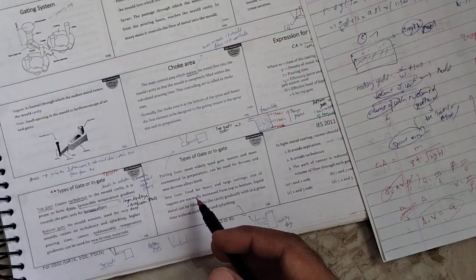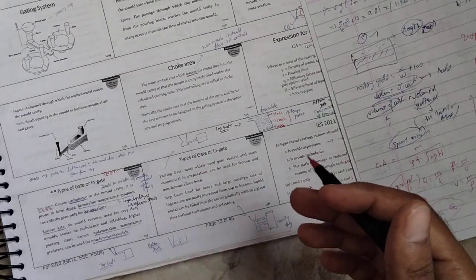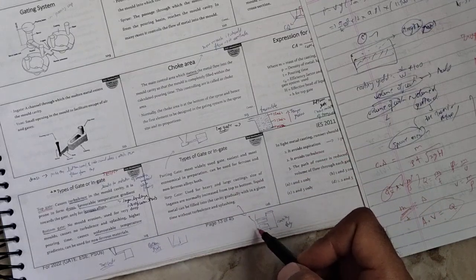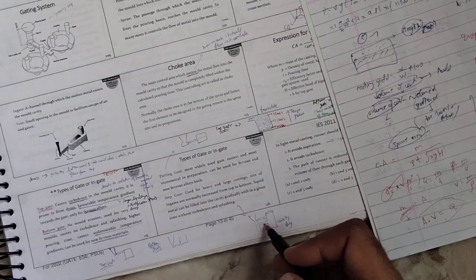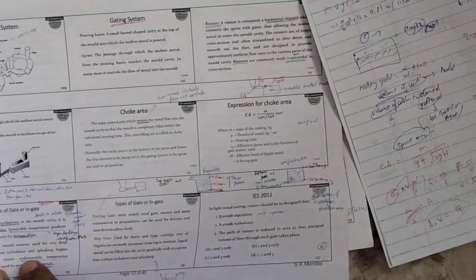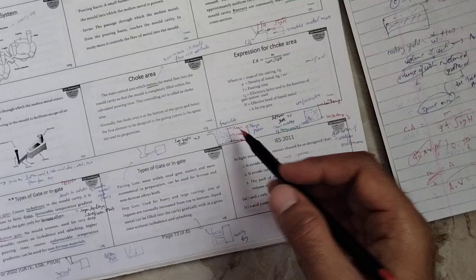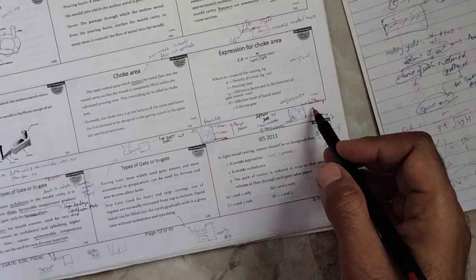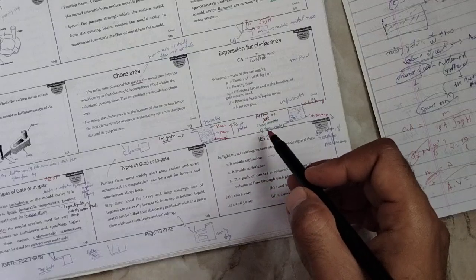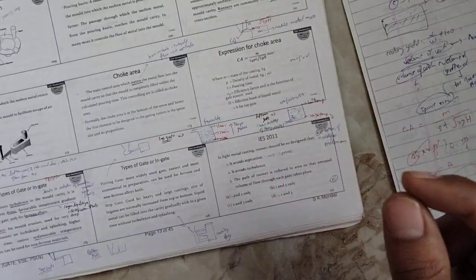So next one is step gate. Step gate is used for heavy and largest castings, depending on the size of the gate. Step gate combines top gating, bottom gating, middle gating, and parting gating. Parting gate is used for the middle section. That's it. I'll explain each and everything. You can see this temperature gradient is much larger: here the bottom will be higher temperature and the upper will be lower temperature. So here the mixture at the bottom, the material doesn't grow in a proper way. So that's why we need to consider this.